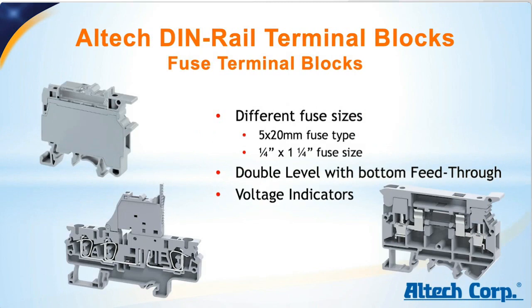A very large group of function blocks within the DIN blocks are the fuse terminal blocks. Fuse blocks are usually used where you need some protection, and they can provide that protection, for example, for output devices of PLCs or all kinds of other modules.